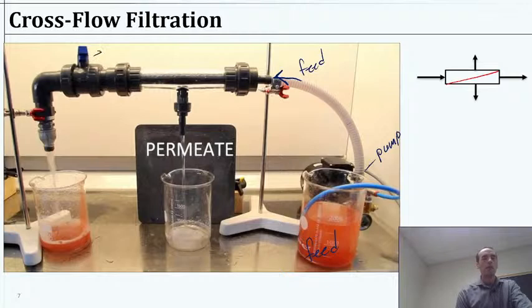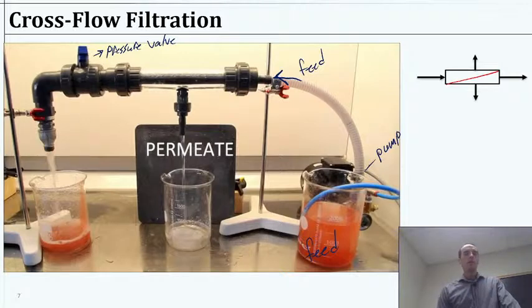So this is likely some sort of a pressure valve letting some water through, but you require some pressure to do so. We see there's water coming out here with still some pressure there. This is going to be our retentate, or the concentrate. So water that passed across the membrane but didn't make it through the membrane. So it moved by the membrane. And the reason I know that is, if you look closely, yeah, it looks like it's showing up there a little bit.